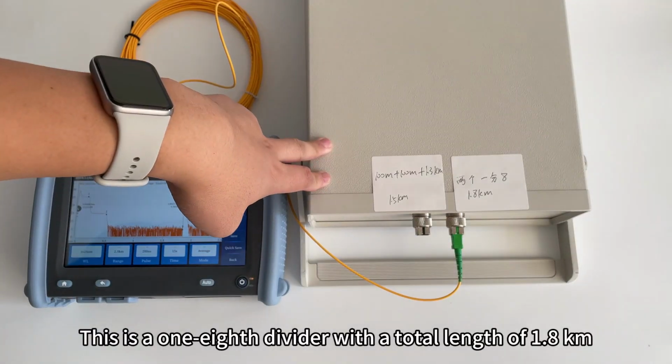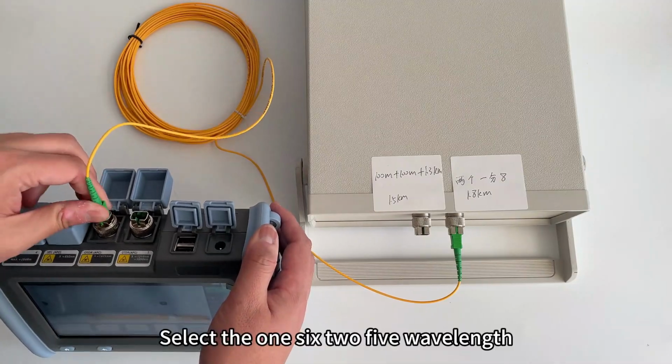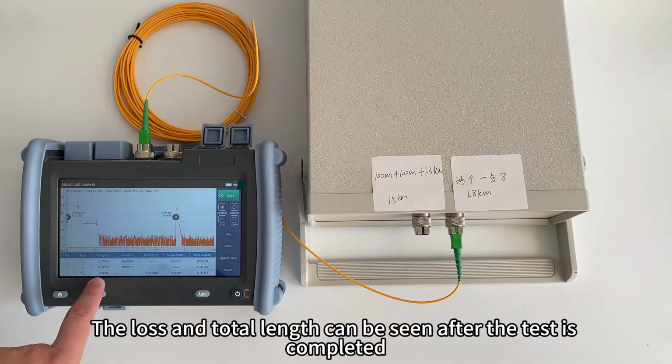This is a 1 to 8 splitter with a total length of 1.8 kilometers. Access wavelength 1650. Select the 1650 wavelength. Click to test. The loss and total length can be seen after the test is completed.